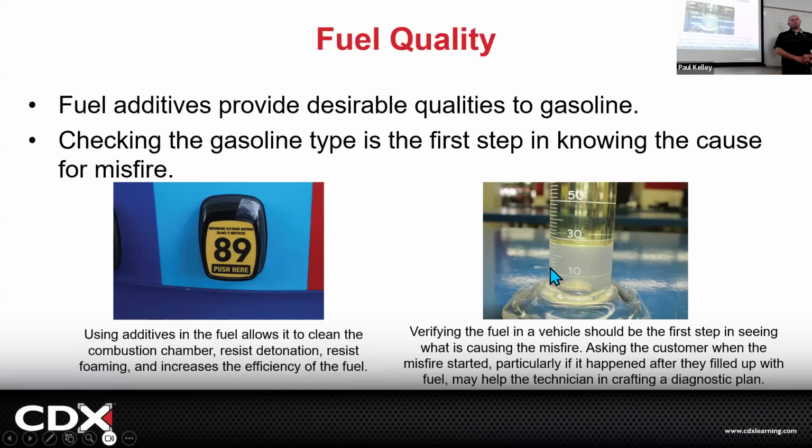This can happen in the shop too, right? So is the fuel good or bad? Sometimes a little hard to tell. If you guys have ever smelled bad fuel, it smells kind of like paint thinner or something. It's just nasty. Your fuel, if you pump it today, it's probably good. A lot of fuel companies will say like 90 days. So you've got 3 months. If you pump gas today, 3 months from now, you better have burned it up and done something with it.